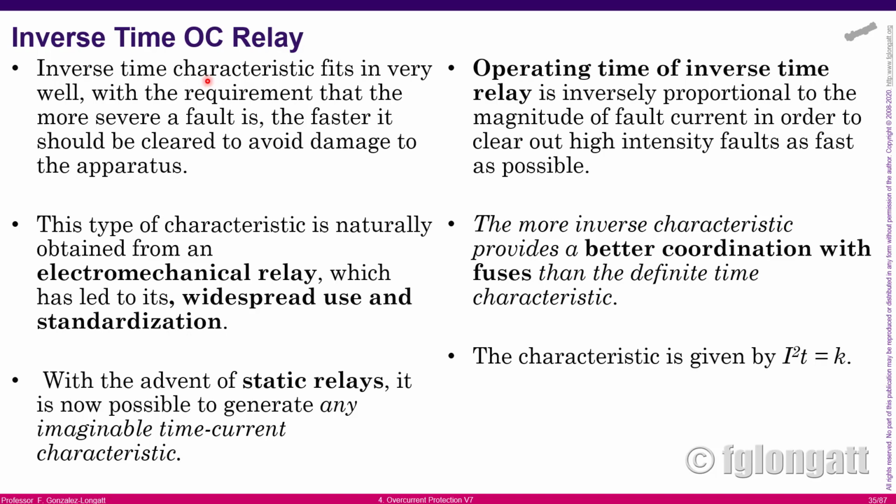The inverse time overcurrent relay was very, very useful for many years, and is still useful inside the power system, because it was very simple to create using electromechanical relays. And that is the reason that from the electromechanical relays is when the standardization starts to push a lot, and then we spread the use of those. With the era of static relays, right now you cannot imagine the different time characteristics that you can create.